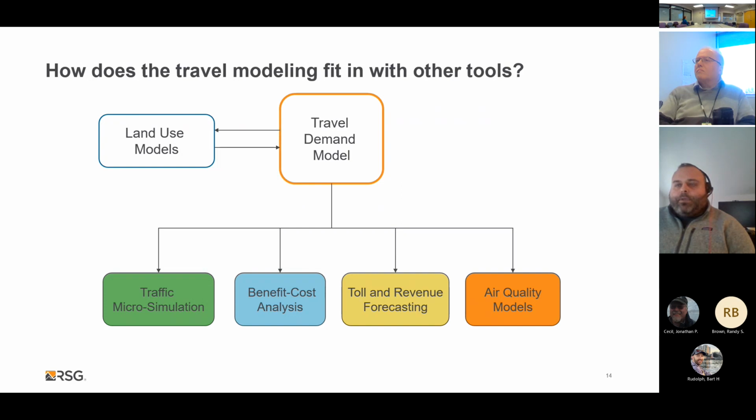So an example would be if you were doing a corridor analysis and you wanted to start looking at signal optimization within the corridor and an individual intersection's ability, you'd want to take the sub area, the corridor, from the travel demand model so you get the right overall amount of trips. But then you want to microsimulate that traffic so you can get operational level details at the intersection level. So the travel demand model isn't necessarily a good tool for looking at individual specific intersections, but it's a good tool to feed into the type of analysis that you might want to do for intersection design.